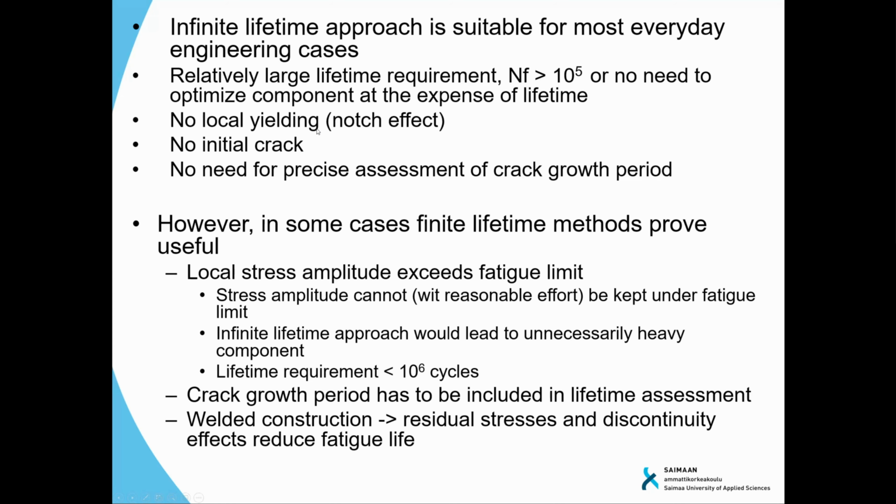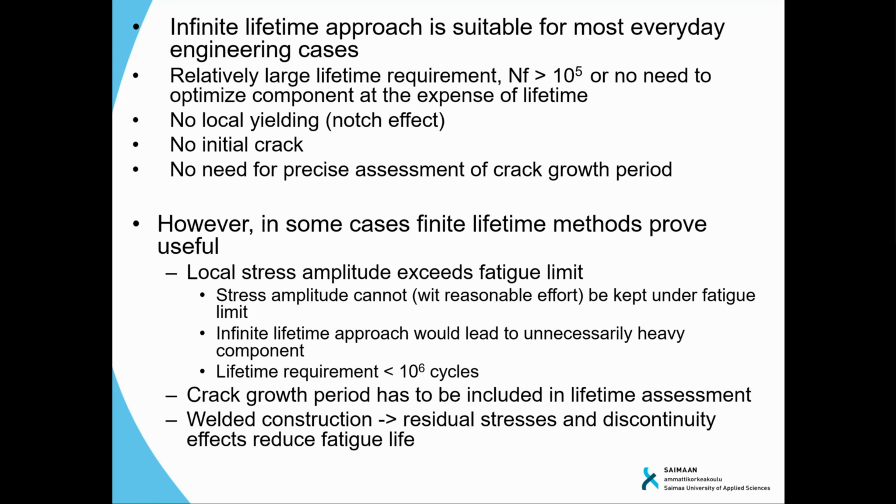Exactly. That is important. So if you know that you have a notch, you have to first calculate the stress, including the fatigue notch factor. You have to use the fatigue notch factor, and if the fatigue notch factor is so high that it will increase the stress level above the yield limit, then you are not able to apply this method anymore. That was an important topic and a very good question. So we just use common sense, basically.